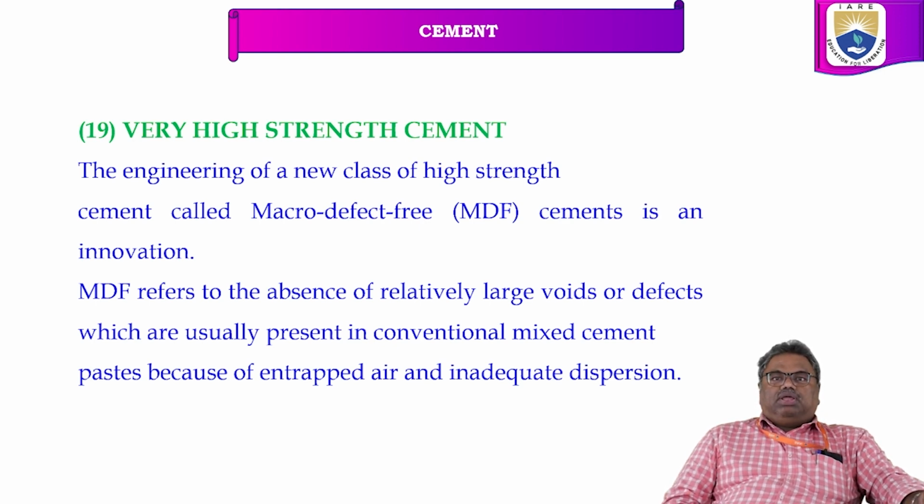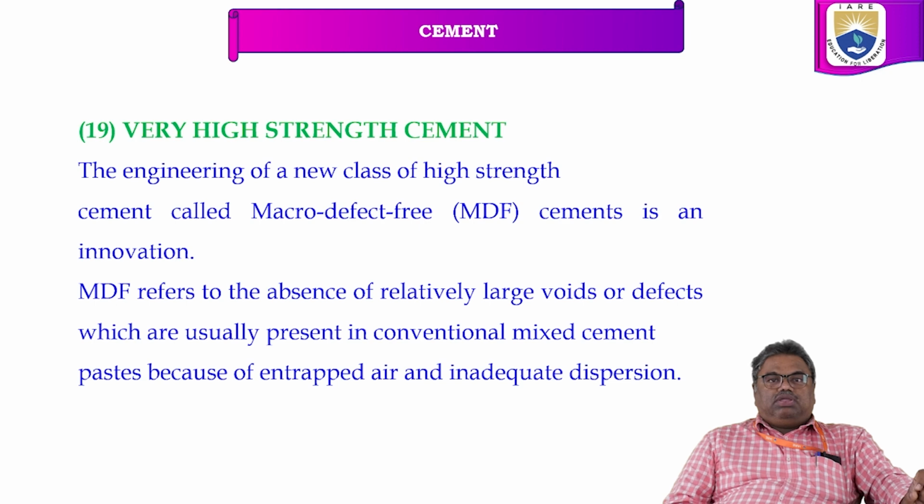Here MDF, macro defect free cement, is one of the innovations in very high strength cements. MDF refers to the absence of relatively large voids and defects which are usually present in conventionally mixed cement paste because of entrapped air and inadequate dispersion. So this is one of the major innovations in very high strength cements.